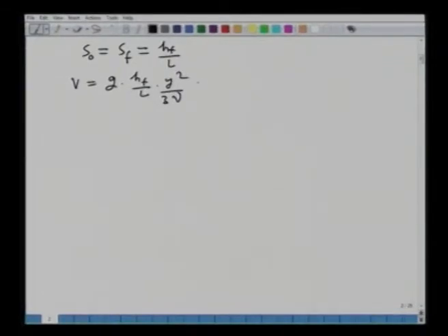That would imply hf, which is the head loss quantity, is nothing but 3 mu over y times L over y times v over g. You can see that we can come from here to here very easily. Now, what I do is I multiply and divide.